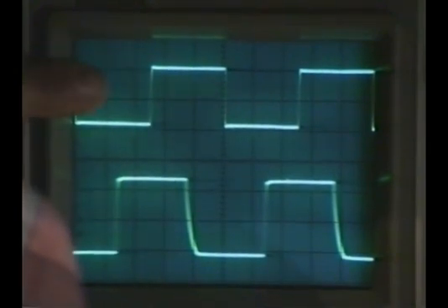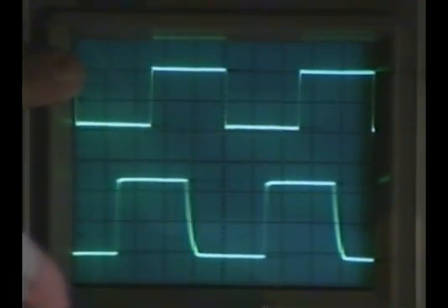I can add a very considerable amount of noise, and it will actually maintain lock. This is, in fact, why FM sounds better than AM, right? If I were to add little noises here, it will lock even when the amplitude of the noise is on the same order of magnitude as the signal, which is kind of extraordinary. And certainly, if the ratio between the two is maybe 10 decibels or more, it'll lock perfectly. So that's an interesting fact about phase lock loops. But you'll be seeing these more at some point anyway.